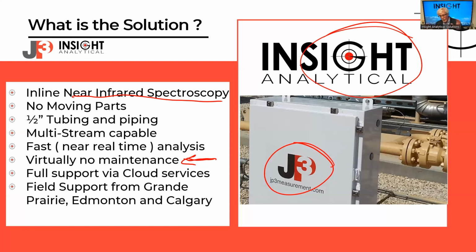We've got lots of customers we can say, look, talk to these guys. They've done exactly what we're doing. Cool things about this analyzer as well, which unfortunately is not shown in this picture: there's a satellite antenna sitting over here. We have a cell modem connection. All the data from it is in the cloud. We can log into any analyzer while it's out there and look at how it's running. We've literally called clients and said, you've got water in the bottom of your condensate stabilizer right now because we can see a water peak in your infrared spectrum. And we run support for it out of Grande Prairie, Edmonton, Calgary.